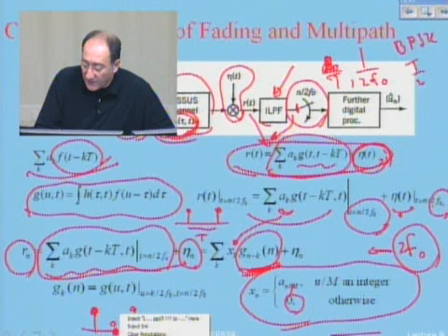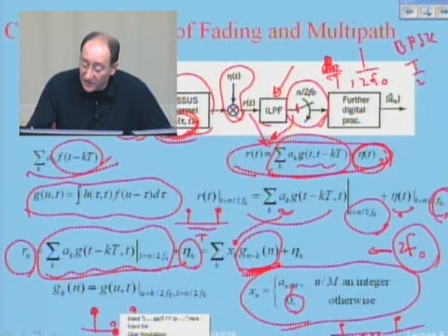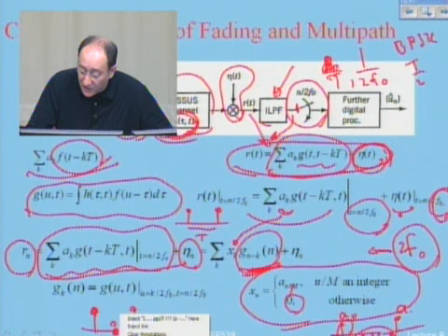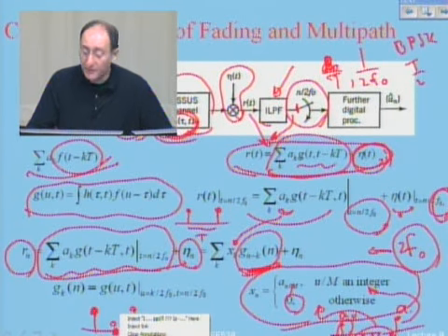Means that I have these transmitted bits. I can take as many samples in between, not necessarily relating f naught with T. I can have m samples per 1 transmitted pulse at the receiver, and these m samples, in terms of data, this is A0, this is A1. In between, I have zeros. These are those zeros. These are non-zero values.